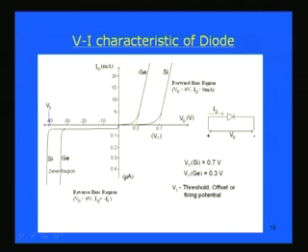It is called Zener breakdown because this phenomenon is actually exploited and utilized effectively in the Zener diode, which we will be discussing later. That is why this is also known as Zener breakdown. For a Zener diode, this breakdown can occur at a smaller voltage, because a Zener diode is a special kind of diode that we will discuss later. It is a very highly doped diode. When you dope it very highly, the breakdown voltage will be smaller. If it is lightly doped, you will find that the breakdown happens at a greater voltage.